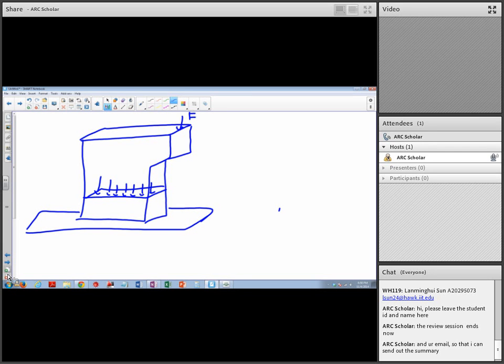the whole part will bend this way, so it must look like this. Because of this force and because of the distance, there's going to be a moment and it will turn it this way. So on this cutting plane, this part will be in tension and this part will be in compression. Can you see this one? When I'm pushing it down, this part is compressed while this part is bending. So there is tension in here. Okay.